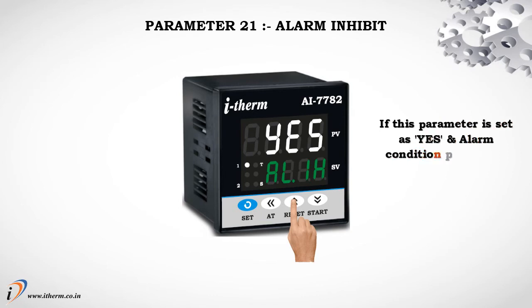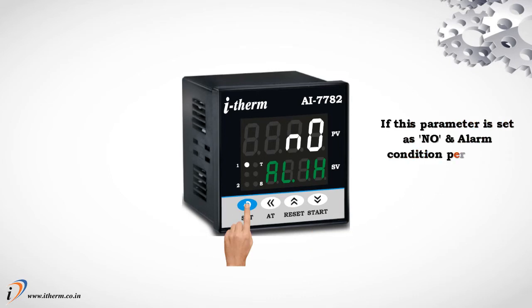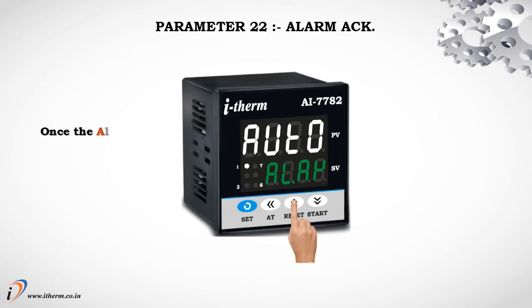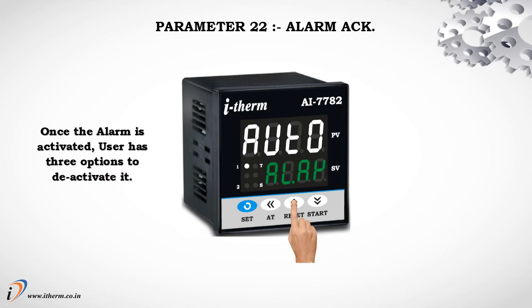Parameter 21, Alarm inhibit. If this parameter is set as yes and alarm condition persists, it will disable alarm output at power on. If this parameter is set as no and alarm condition persists, it will enable alarm output at power up. Parameter 22, Alarm acknowledged.